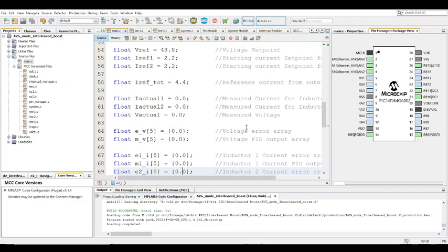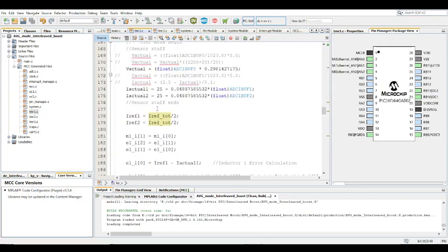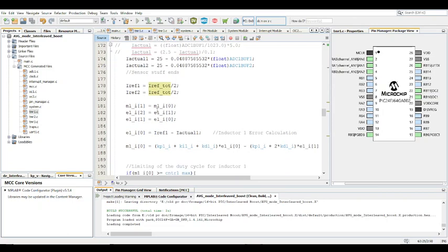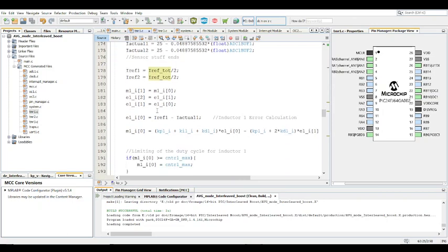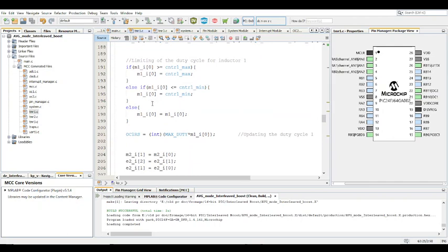And it's important to note that you could also use a 2-pole 2-zero compensator or a 3-pole 3-zero compensator for this, but I find that the PID has a good balance between speed and ease of determining the coefficients, so it's more flexible and easier to use than a 3-pole 3-zero compensator, where you have to be a lot more precise with your design. You actually have to calculate those values for a 3-pole 3-zero compensator.